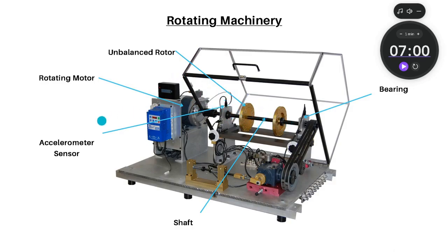machine. Then we have a sensor. This sensor will detect the vibrations produced in this shaft. So the sequence will be like this. First of all, the motor gets started. The rod is getting rotated, and to test the vibrations, initially the vibrations are less. So to test the machine, we add some mass here. After adding some mass, some vibration will get produced in the machine.